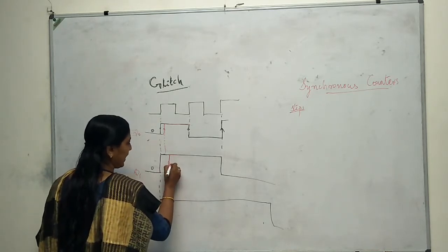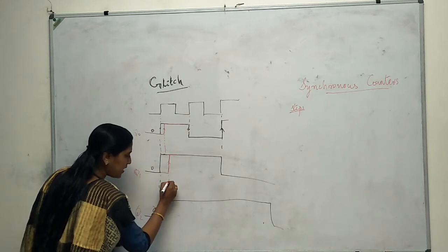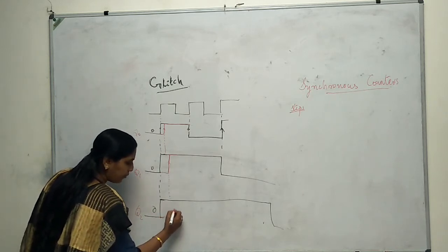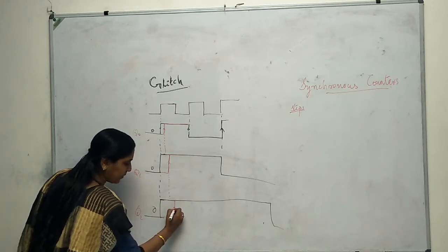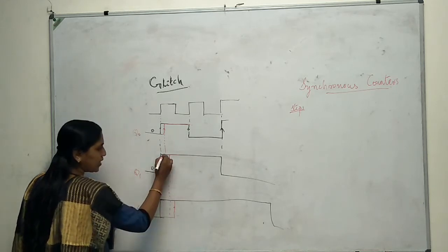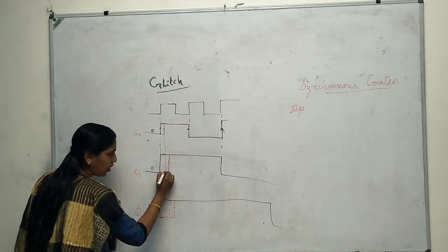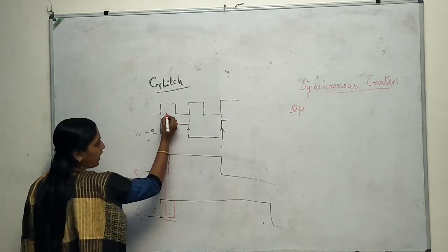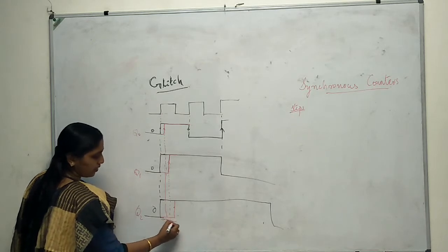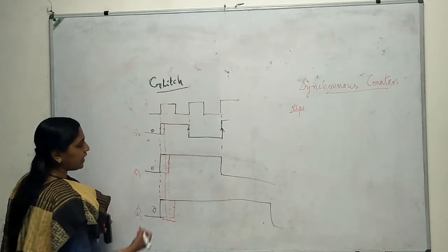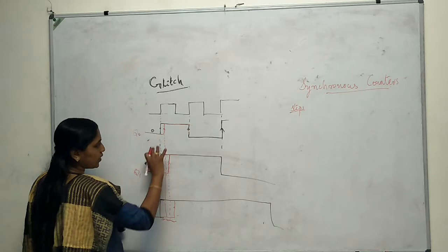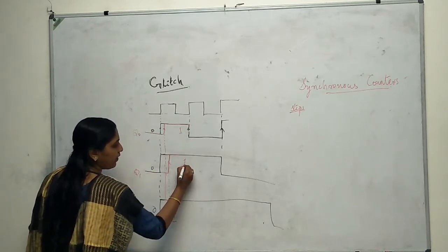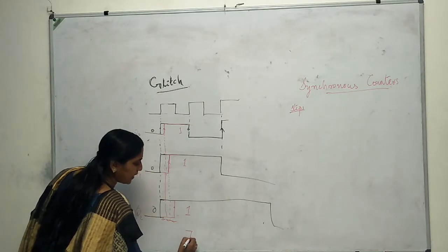Here also, since we get the input at this time, only after some time will it get activated. So here also there is some delay. Actually there is a total of this much delay between the current clock and the final output. Here we are assuming the state goes from 000 to 111, so we are expecting 7 here.